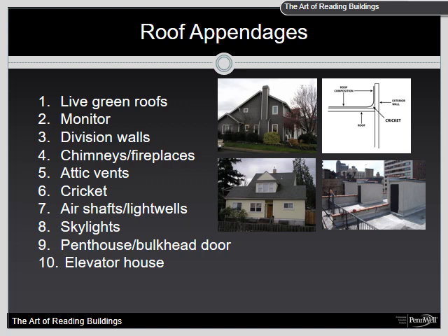Now for a cricket, I haven't seen one personally myself, but the text calls it this. A cricket is the junction of a vertical member, such as a skylight riser or parapet wall, and a horizontal member, such as a roof, where the intersection junction is covered by a roofing material. Its purpose is to keep water from running into and down the vertical member.